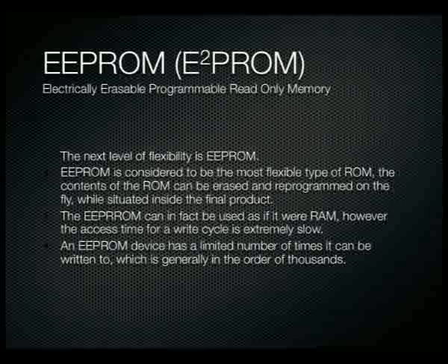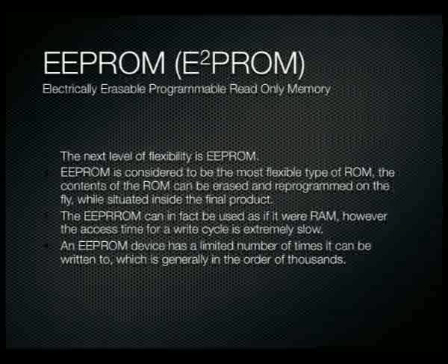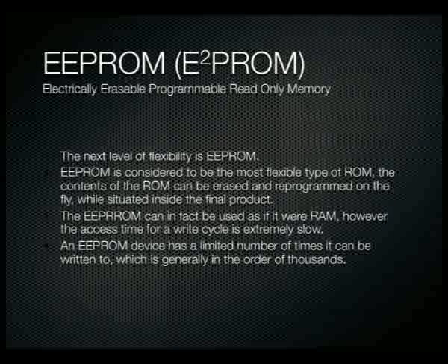The EEPROM can also be used as if it were RAM. However, the access time for a write cycle is extremely slow with EEPROM, because if you want to write to a memory element in an EEPROM, effectively you've got to erase it first and then write to it. So there's that two-step process of an erase, then a write, which can slow down the entire write cycle.